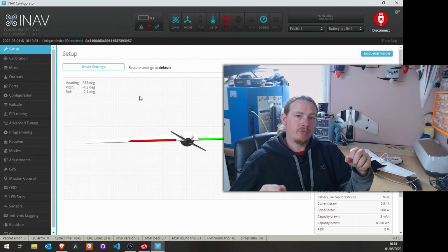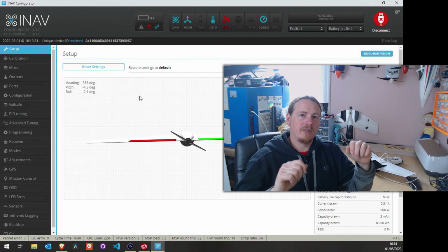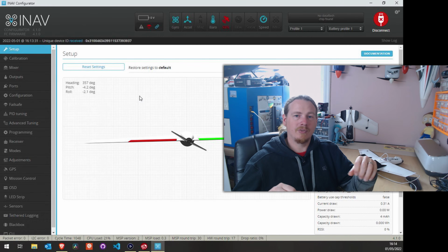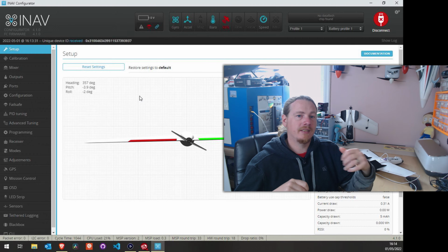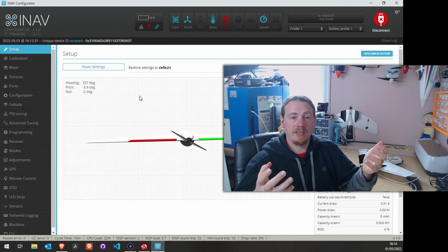If you see people shaking the plane and then throwing it, they're doing auto launch wrong. You're not supposed to shake it at all. By triggering the launch, you can induce I-term wind up, which will mean when you actually throw the plane, it's slower to react and could end up making it crash.